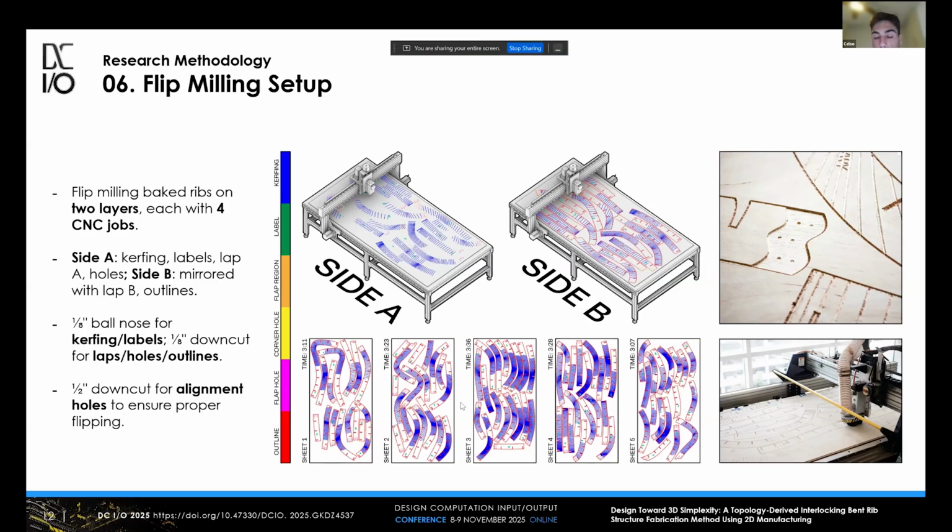In this project, we used a 3-ply, 3 millimeter plywood sheet. Therefore, what I had to do regarding the depth of the cut was to leave the center ply intact, and we cut through the first and also the last ply of the plywood.